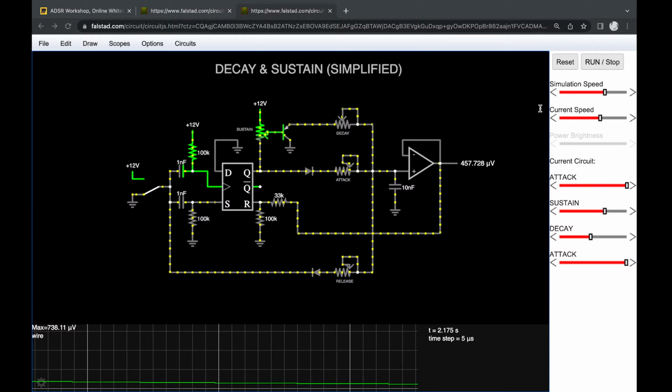Ian says, just curious, if you're going to put an op amp at the end, why not just use that to amplify the output a little rather than do the whole voltage divider to reset thing? Well, basically because you do not want the output of the envelope to be super high, right? You want the output of the envelope to be 8 volts at max. That's the standard. So it's better to divide it down at the reset input than to increase the gain of the op amp.